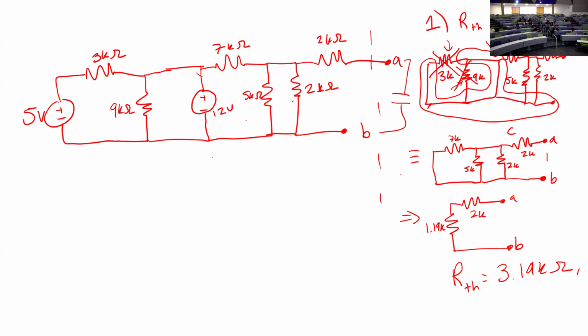Yeah. So what I combine here is in this first one. So I'm looking in this circuit. This 3 kiloohm and 9 kiloohm are in parallel with a wire. So if I were to solve this, it'd be 1 over 3 plus 1 over 9 plus 1 over 0, right? Which blows up my calculator. Math is very unhappy with that.